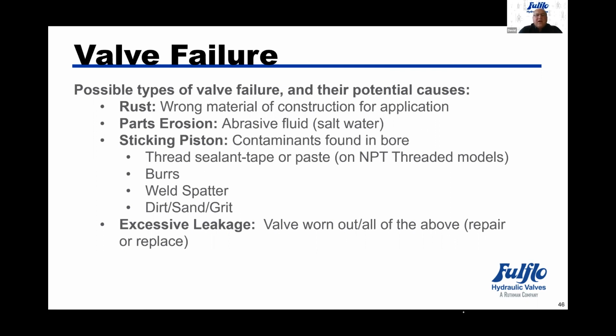Once the application has a clean fluid, usually the valves are installed and no one ever has a problem with them. When you do have the problem and the piston is sticking inside, you're going to get excessive leakage. The valve will be worn out, maybe due to salt water eroding the part, where the valve's just not going to close off.